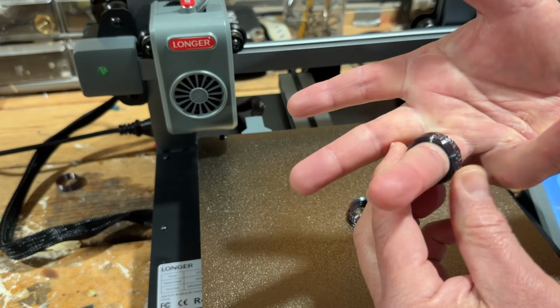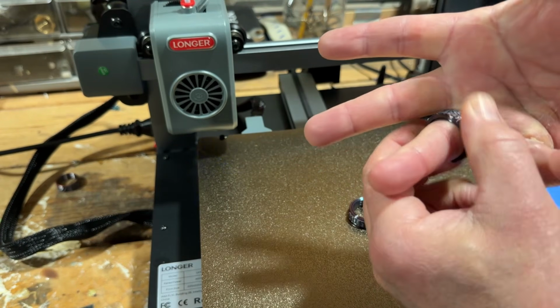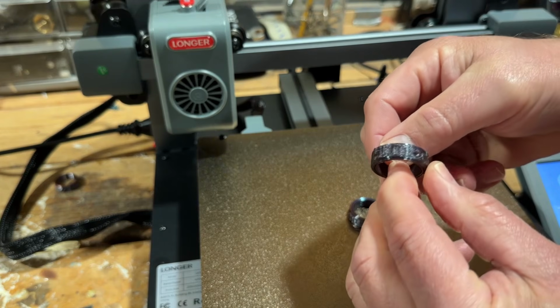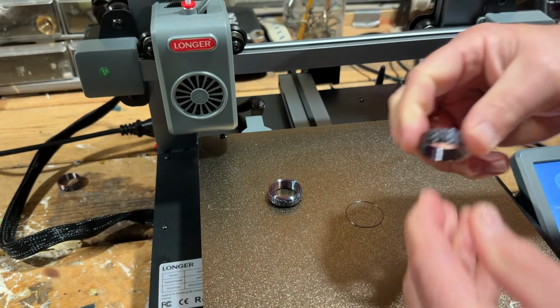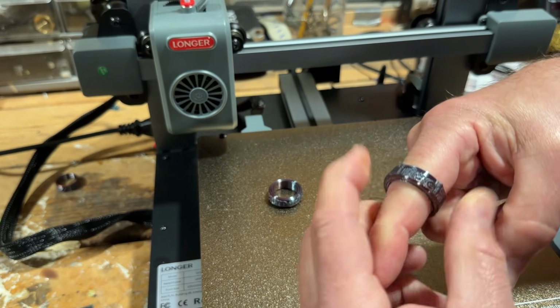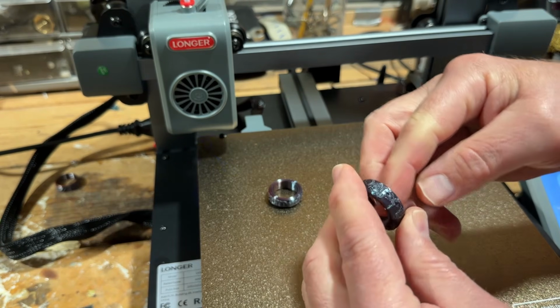Alrighty, so ring complete. Once again, this was the first one. It was tight. I had to really work to get it to open up, but as you can see, it does still spin. Words are on it, and it turned out super fun. Love this filament. Let's snap off the new one. Check it out. It spins immediately. So by switching to that 0.25 gap in between them, that worked like a champ.